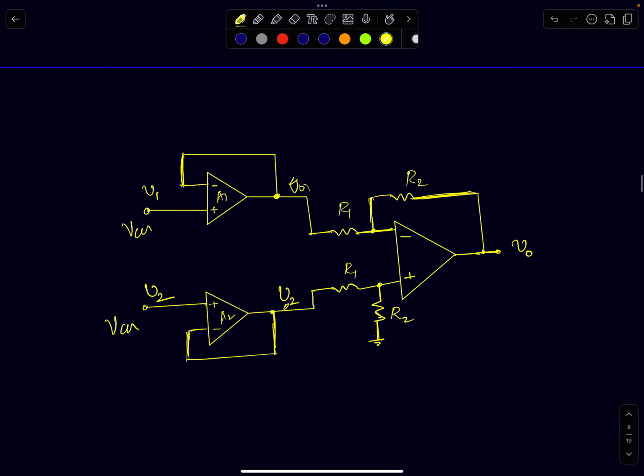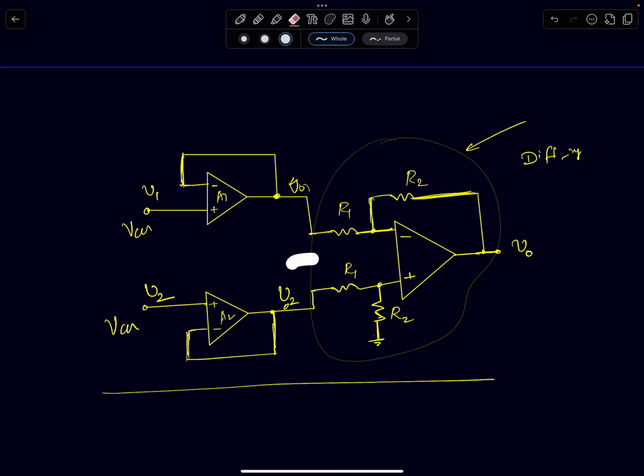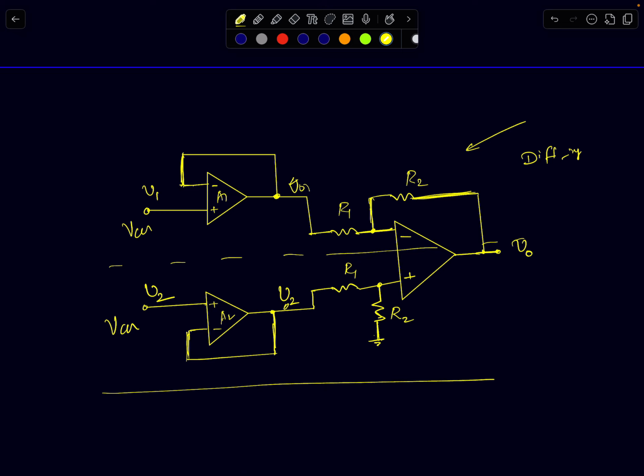And that is what I've shown here. The first stage, the second stage, that is the familiar differential amplifier we discussed in the beginning of the lecture, a simple subtractor with a finite gain. What I'll do is take that circuit, and instead of applying the input signals as they are, pass them through 2 buffers, 2 voltage followers, and feed them as inputs. Now the circuit has good differential symmetry. The signal paths go through the same op-amp and come at the output. There is some axis of symmetry around which the circuit has some kind of symmetry.